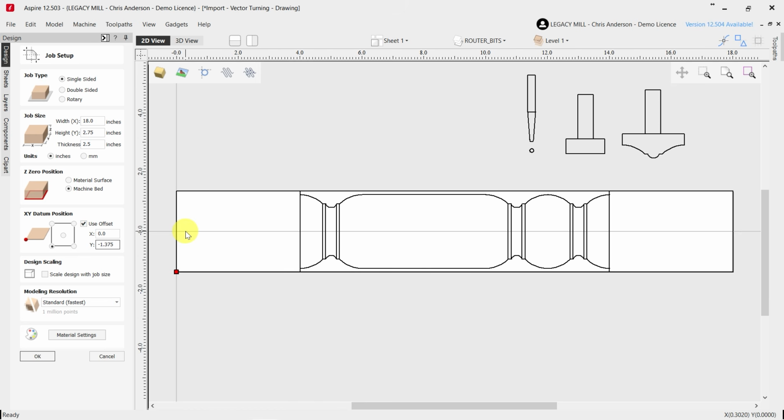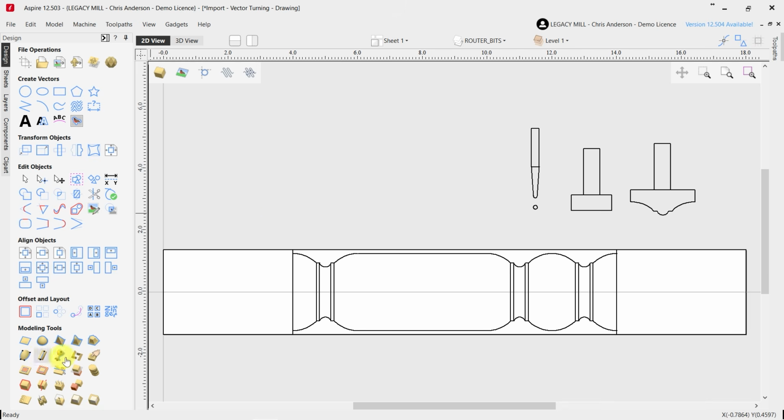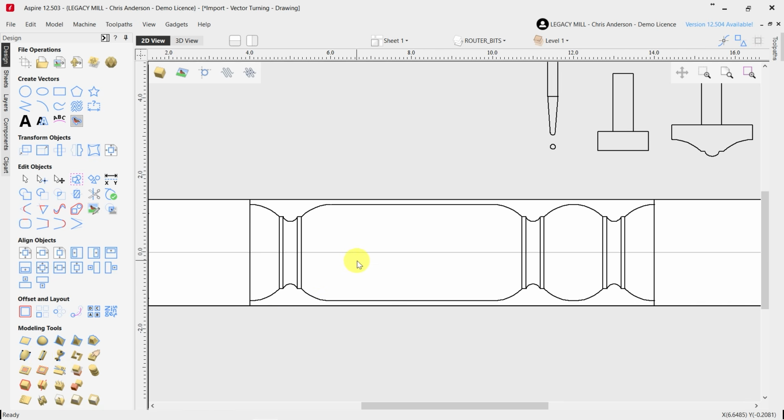There you go. You can see it now puts the Y down the dead center of our spindle, which is exactly where we need it to be. So that is the only critical step that we needed to produce for this process. It doesn't matter where our Z0 is located, same as the material thickness. So those are the only changes that we had to make to this part. So let's push OK. And now let's lay out a design of what's going to take place.